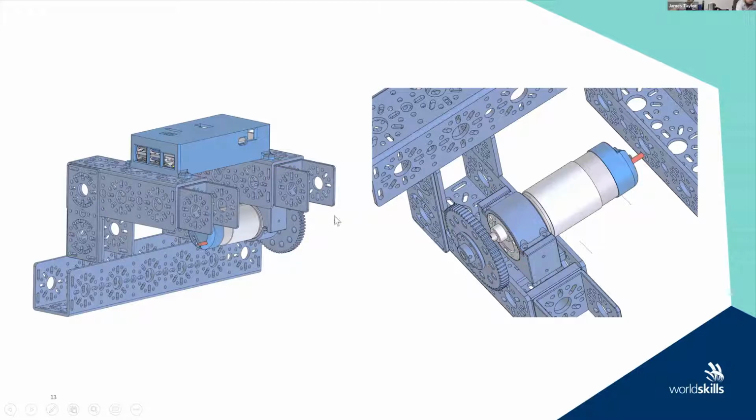I do not have the fasteners on that CAD because it would get a little bit too complex to put each fastener in. So just remember, you're going to use your 12 millimeter socket head cap screws and use your KEP nuts for this, as opposed to what we talked about with the nylock nuts, because I'm going to assume that you wish to disassemble it as you go forward. So you're just going to build that frame subassembly.